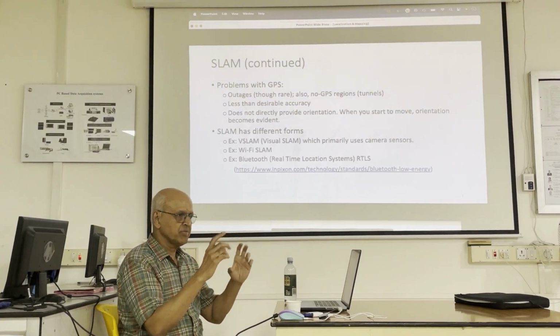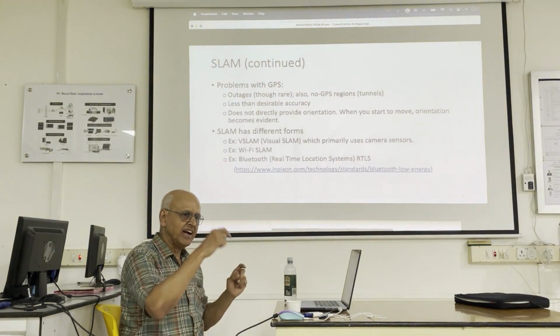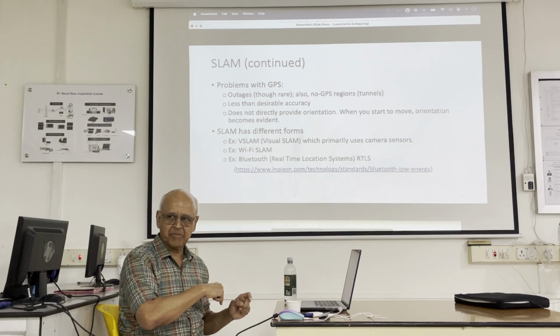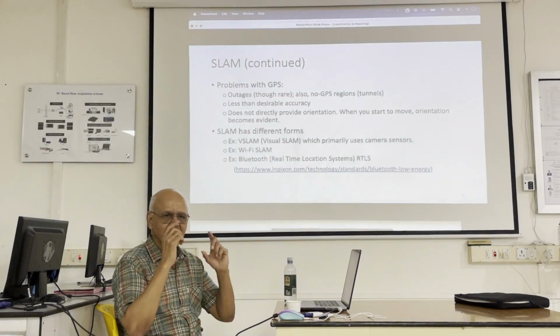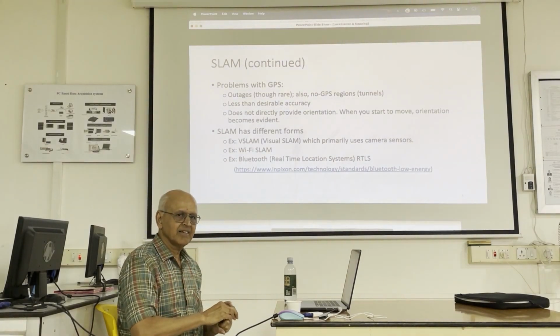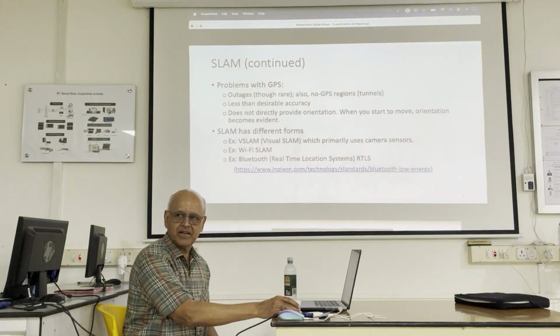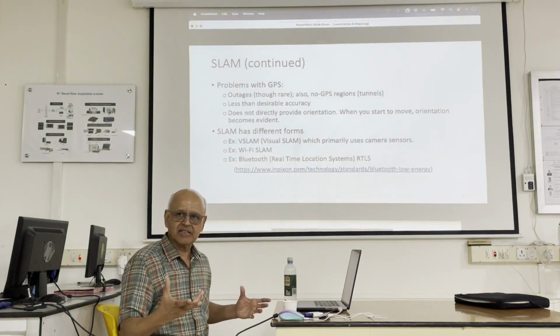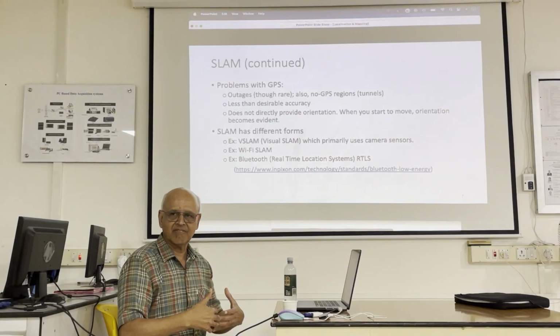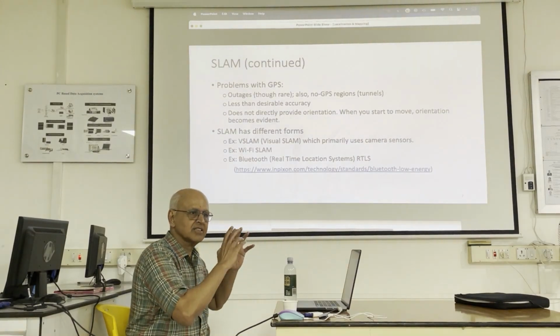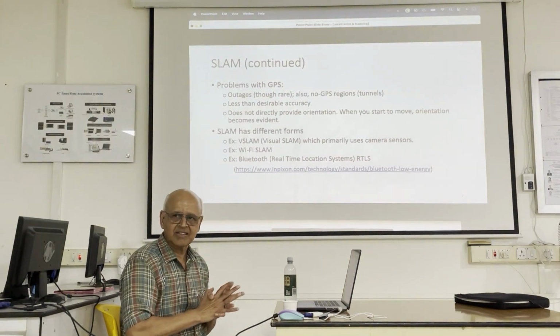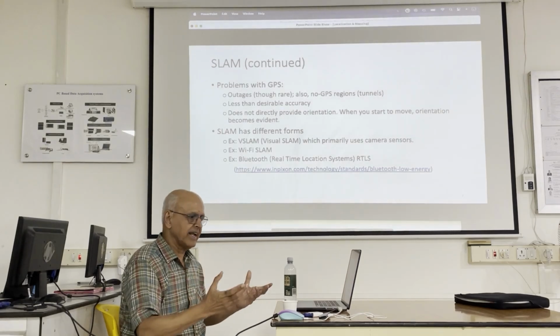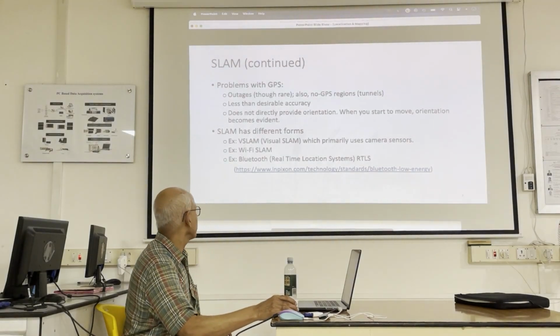Maybe you can use LiDAR and odometry and the camera. So V comes from the visual, traditional camera. It looks at obstacles in the environment and figures it out. So that's another sensor value to fuse. This is multi-sensor fusion. So you throw in a camera, it's just an extra thing to fuse.